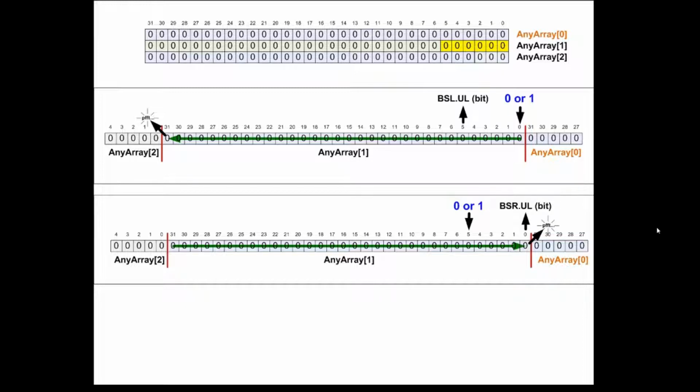So for a left shift, if we have a length of 6, then we are really only working with bits 0, 1, 2, 3, 4, 5. That's 6 bits, length of 6. Now, whatever values that we're bringing into bit 0 and then shifting left, when they get to bit 5, that's the end of the length.